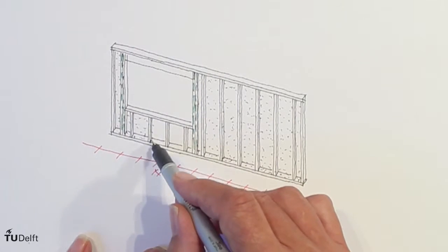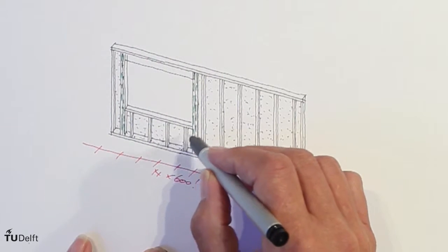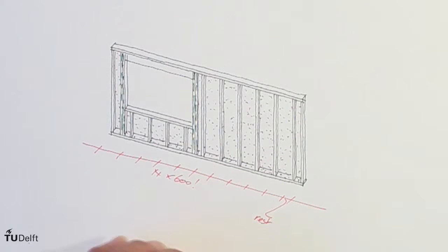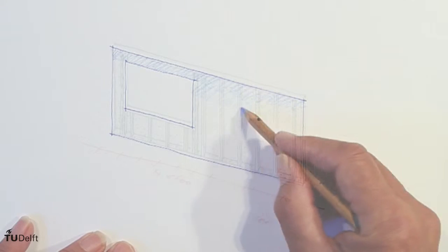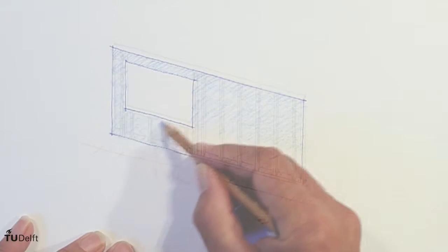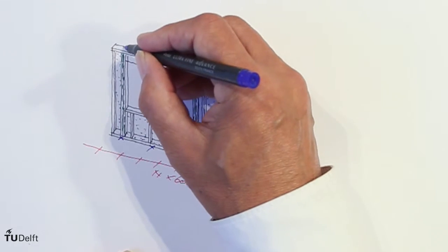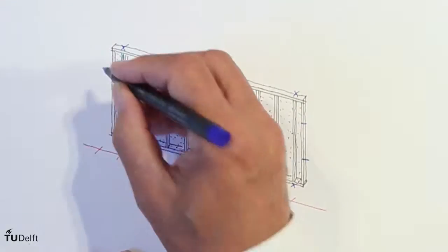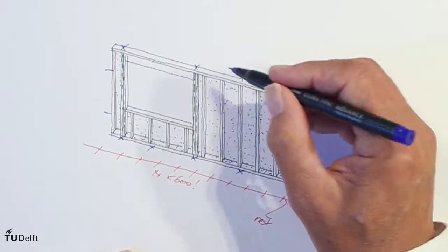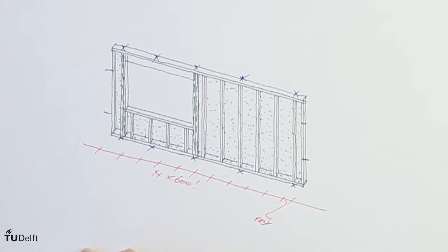Between the studs, thermal insulation material is positioned. On the inward side of the insulation, a vapor barrier is needed, and on the outside, a bladder membrane protects the timber and insulation against the damp and moist in the cavity. The element is connected with a series of anchors at the bottom and the top. At the bottom, structural hinges, at the top, rollers.